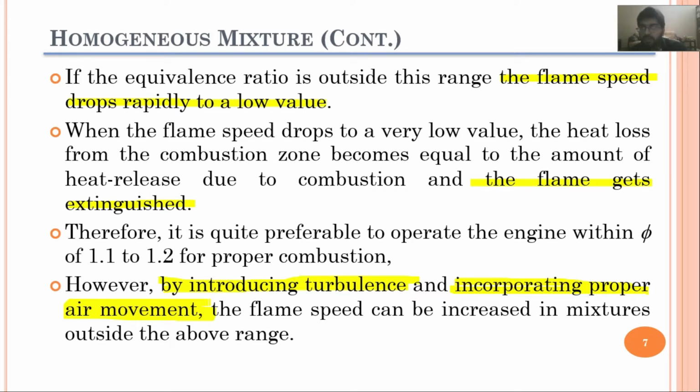However, for example, if I have a piston in which a deflector is incorporated, this will produce greater turbulence, and we can have higher flame speeds in such IC engines. So turbulence can increase the flame speed, and turbulence can be increased by improving the design of the combustion chamber.